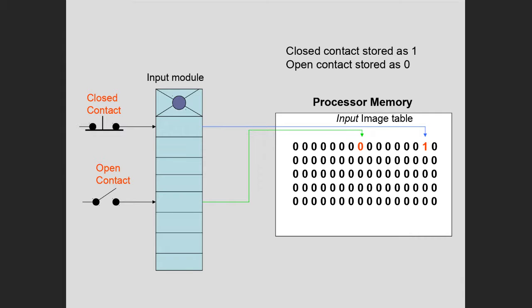And these are the doors right here. Here's a door, here's a door. These are those doors you can open up. And if you open it up, what you see is screw terminals connected there, right? And so this switch right here is closed. And so this is mapped to this particular bit right here. And so since it's closed, there's a 1 in that table.